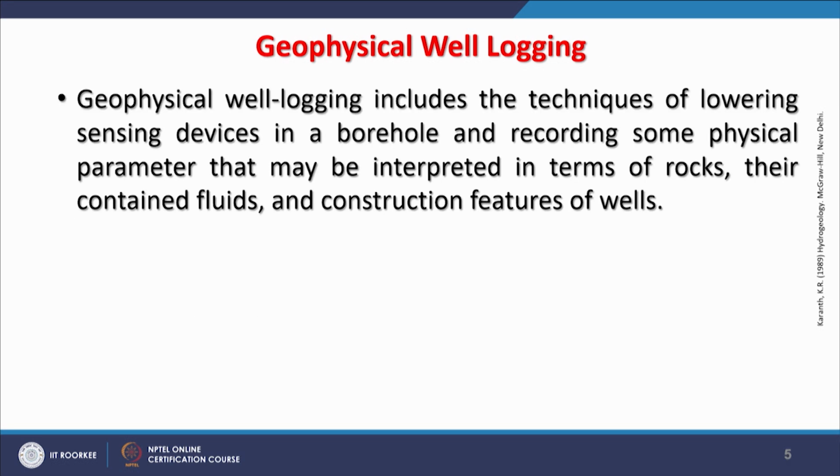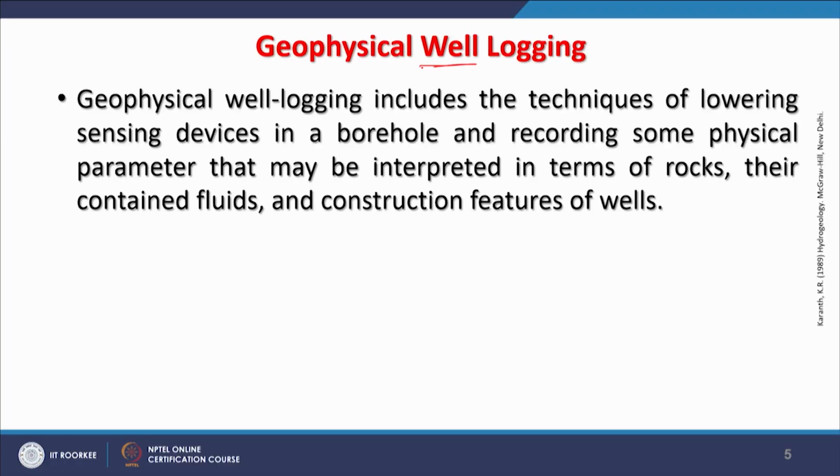Now, we come to the next discussion in this session, in this lecture or video, that is geophysical well logging. So, surface geophysical methods we have discussed, and almost the same way subsurface geophysical methods, or geophysical well logging, is done. The only difference is that there you were doing everything on the surface and trying to get information about subsurface conditions. In case of surface methods, you are putting all instruments on the surface, but here you are putting all instruments inside the bore well, and that is why it is called well logging of a bore well.